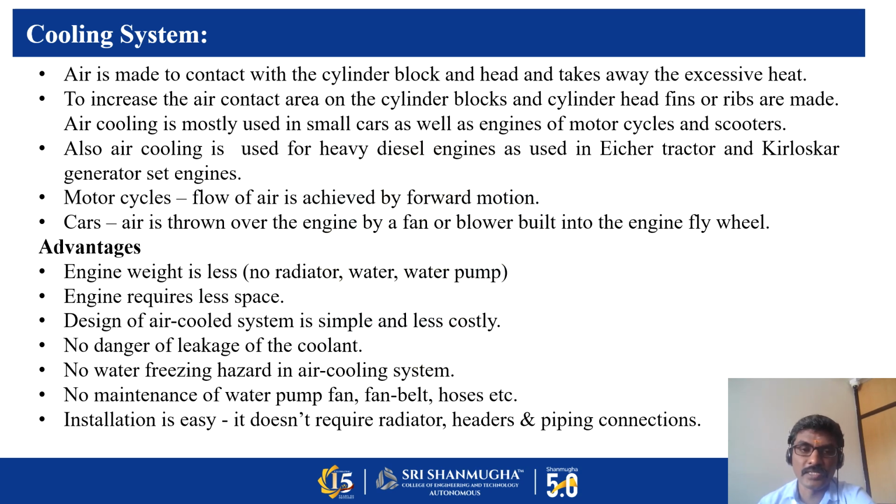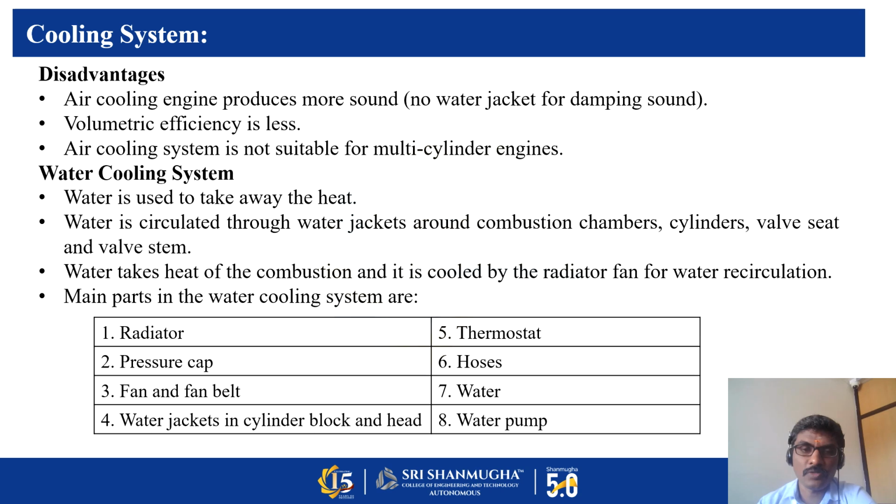Advantages: engine weight is less, engine requires less space. Design of air cooled system is simple and less costly. No danger of leakage of coolant, no water freezing hazard, no maintenance of water pump. Installation is easy. It does not require radiator, heaters or piping connection. Disadvantages: air cooling engine produces more sound. Volumetric efficiency is less. Air cooling system is not suitable for multi-cylinder engine.